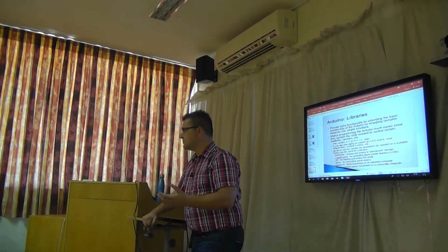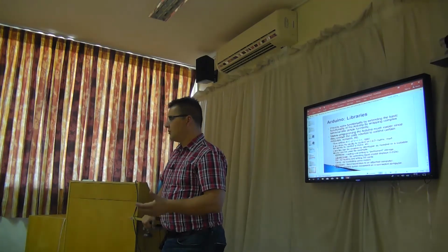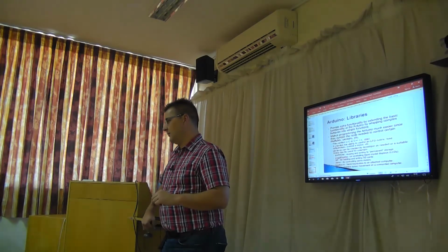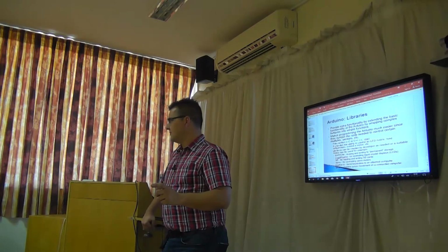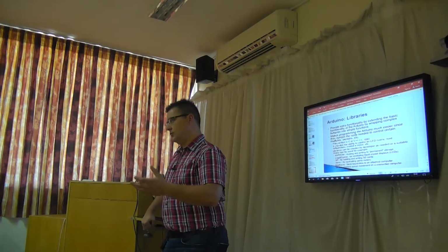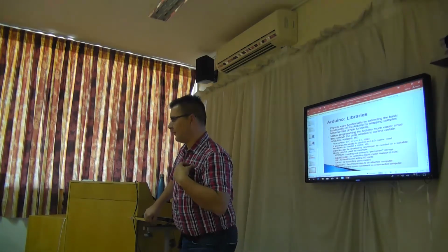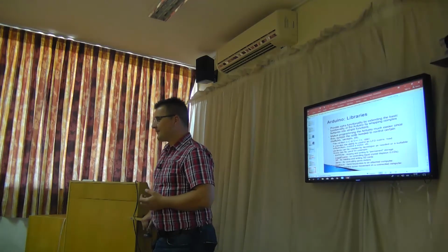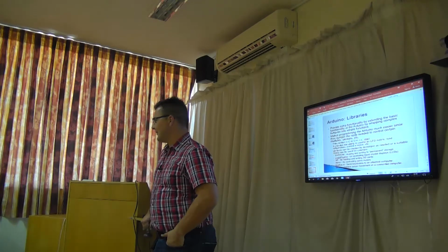Now, I used a transistor and a relay, because you can't directly connect a relay to an Arduino. It doesn't provide enough amps from one of the pins to directly power it. So that is what I've done with it. Now, what would you do with it? What small project would you play around with on something like this?